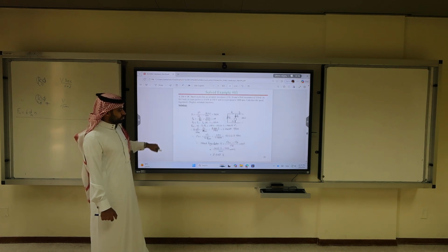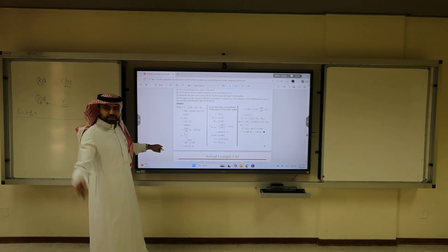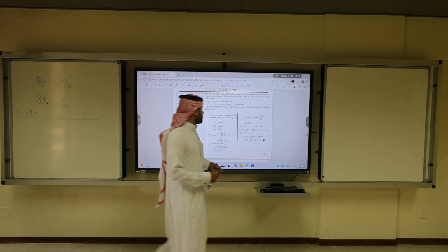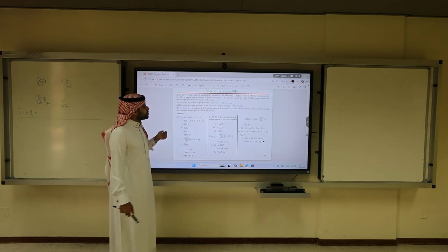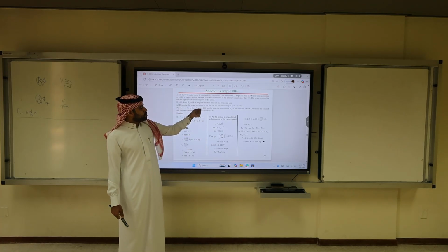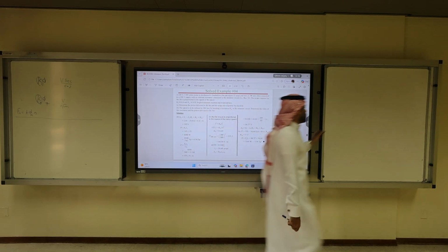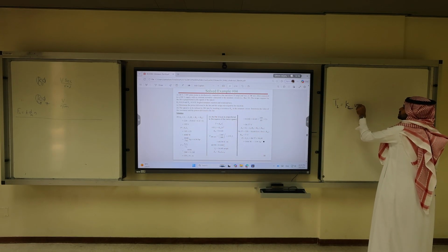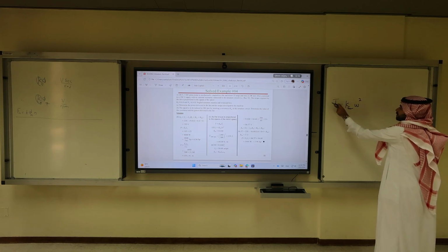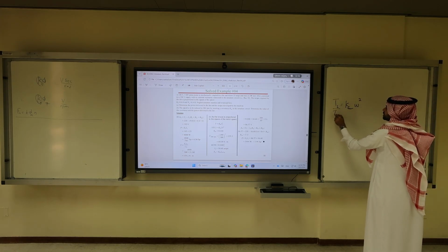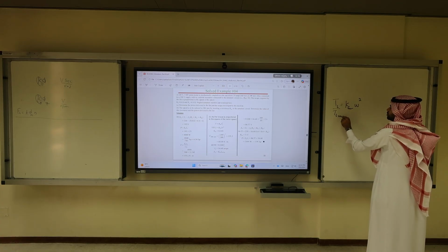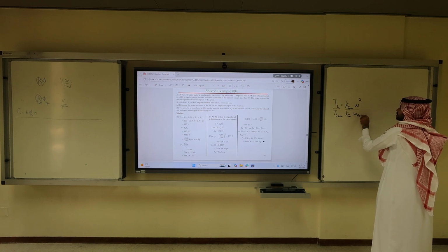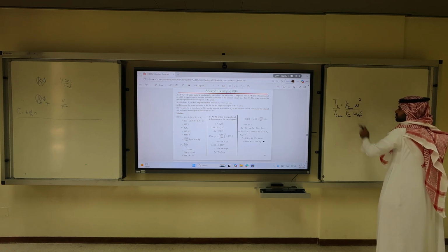It was a fan load. Okay, because it's a fan load, thank you. Because it's a fan load, the speed is to be reduced to 200 RPM, you're right, thank you. So the load torque is K of the fan times omega squared. We have two different torques, so we divide TL new over the constant of the fan times omega new squared. So that's why the ratio is proportional.